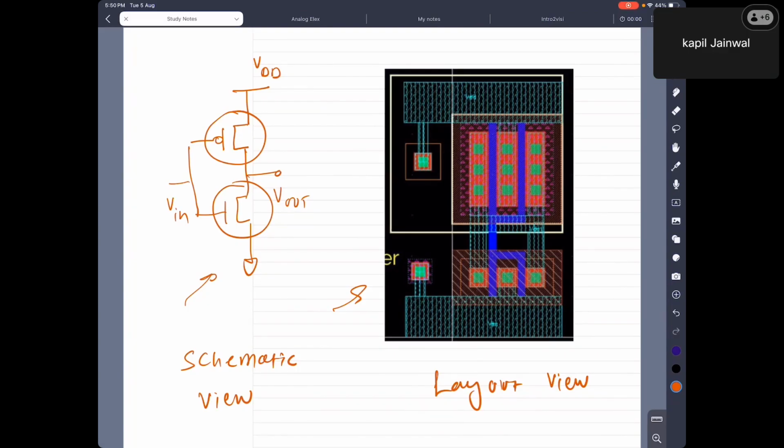Similarly, we can go to very complex equations. In this circuit, if I want to know the currents and the node voltages, and I know the equations which define this circuit, I can have all the values. I can solve these equations and get the node voltage, node current, the current between two terminals. These are very specific things, but we can even do more complex analysis like noise analysis, frequency analysis, delay, transient analysis. All of these can be done, but we need to have those equations. And once we have multiple equations, we need to solve them, just like solving a differential equation or higher order equations.